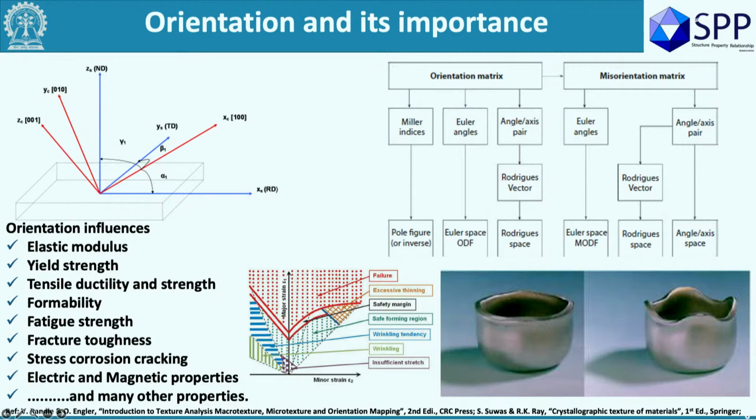Fine. One answer is that's the symmetry. That's not the symmetry of the specimen as such. That's the symmetry of the deformation that you put there. So if you consider this rolling, which is a plane strain deformation, you can imagine that something is pulling things in the rolling direction and something is pressing things in the normal direction. That's why these are important, correct? So this first why was very much obvious. Now the second why comes: fine, I understand that this is related to the symmetry of that particular deformation system, then what?